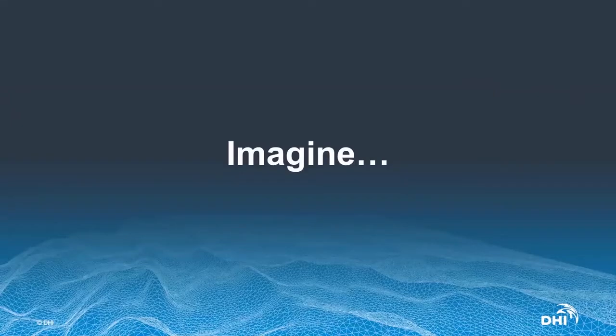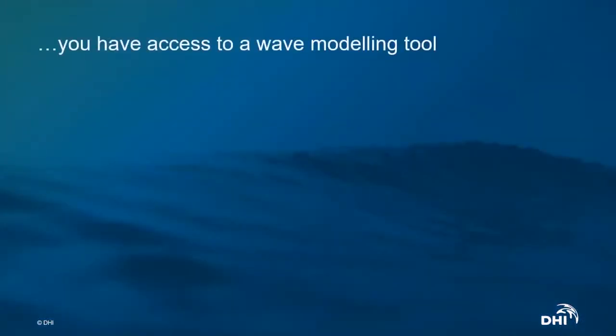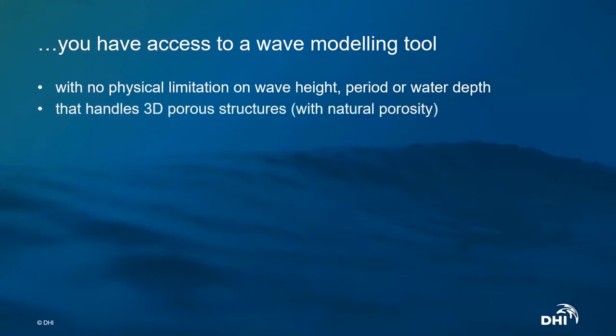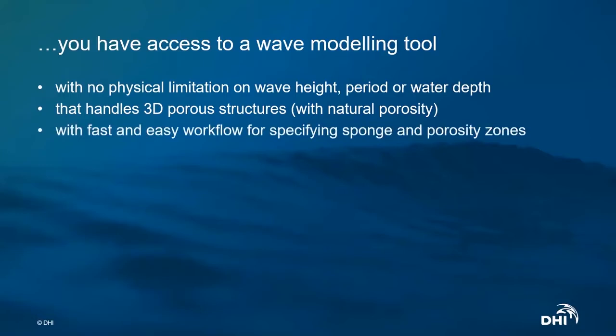First of all, I will try and help guide you to imagine that you have access to a wave modeling tool that has no physical limitation in the wave height, in the period, in the depth. There's no kh limits, and it is able to handle three-dimensional porous structures where we are either trying to resolve some of the flow, or approximating the flow using porosity models.